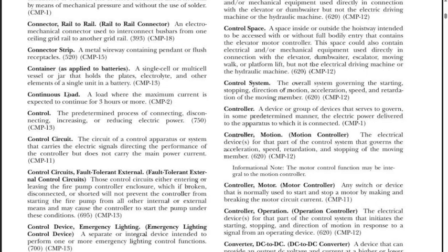This is what this is saying. And what we call that is a continuous load, a load where the maximum current is expected to continue for 3 hours or more. And I would highlight that. I would highlight 3 hours or more, because that's the specific number. Not more than 3 hours, 3 hours or more. Those are two different things, especially when you're arguing law.